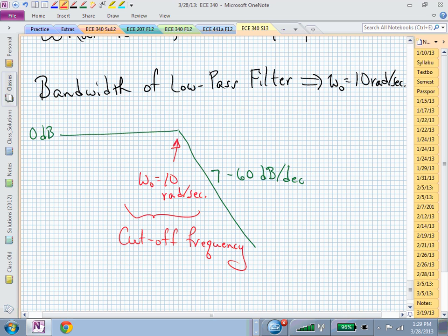So what? We wanted capital T. You haven't told me what T is. You've told me the bandwidth. Who cares? Well, that's important because you want to preserve this behavior. And what are you trying to preserve? Well, you want to preserve signals, sinusoids, that are going as rapidly as 10 radians per second. And we just found out that's not very rapid, is it? That's less than 2 hertz. But 10 sounds bigger than 2, but that's in radians per second.